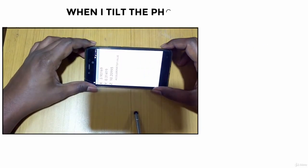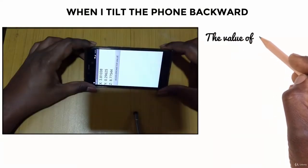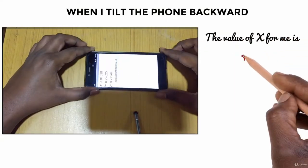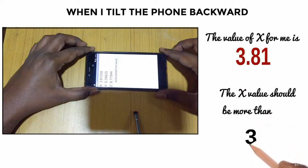After that, if I tilt the phone backward, then the X value is 3.81. So if I want to move the robot backward, then the X acceleration value should be more than 3.81 or it should be more than 3.